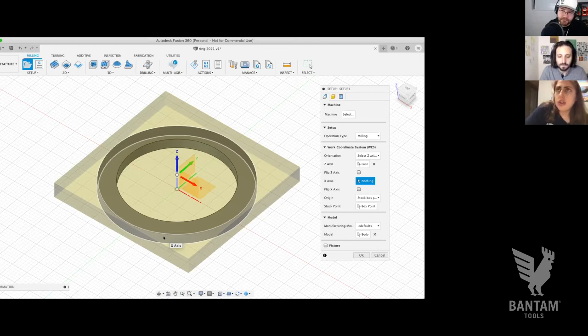And the other thing too, to your point, Tony, it's like locating something within a certain space, right? If you've done any digging in the support guides, there's a common graphic that we have of machine offsets, where the front left corner is home base for the desktop PCB mill and the desktop CNC milling machine. And then from there, everything offsets from that point. So when you run your material probing routine or you orient your plan, everything is going to be based off of that corner.